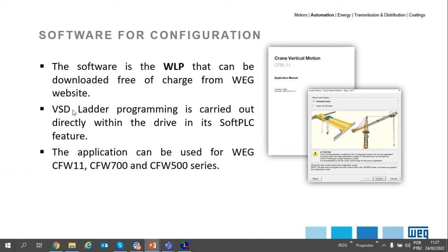And as you could see, the VSD ladder programming is carried out directly within the drive in its soft PLC feature. It's important to mention that the WEG VSD has a soft PLC feature, which is basically a PLC internal to the drive. For that reason, it's not required to have, for example, an external PLC to configure the crane application. You can do that directly through the soft PLC.